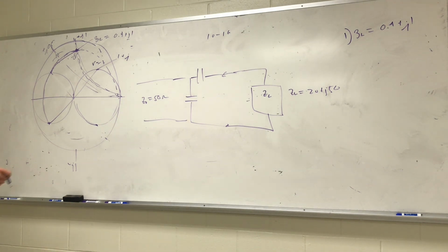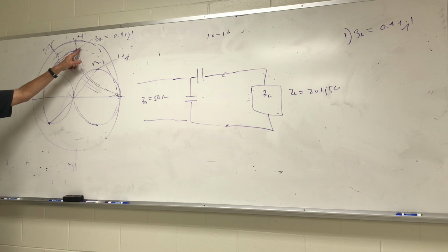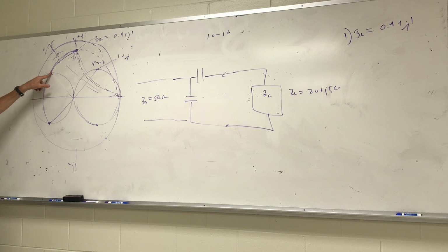Do you understand? If I'm here where I entered, that is the impedance domain. That's impedance Z, right? If I'm adding a capacitor, I will have a minus J impedance. I could go to here, right? But I could keep adding a larger capacitor and get it down to here. Do you agree with that? Why? Because this is going to have a minus J value, right? We started with a plus J. If we add a capacitor with a minus J that was so large, it would not only bring it to here, 0, but it would also bring it down an additional value. Do you see how these are minus J values? Or not?